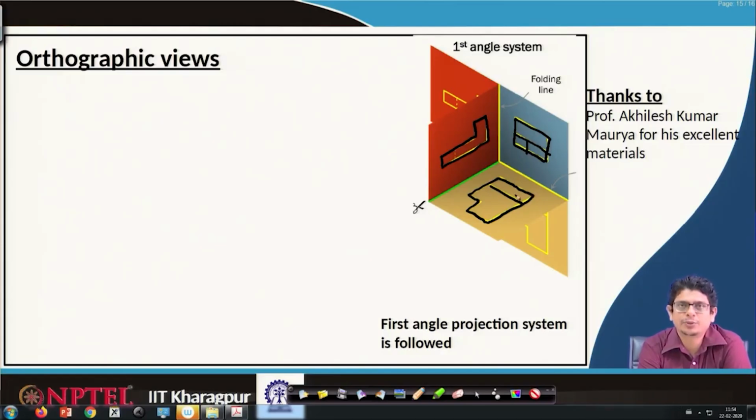The standard procedure is to first decide the vertical plane front view, after that go with the top view on the horizontal plane, and after that construct the side view, the profile plane view. So, here we construct the left side view and represent that. This is the way we go ahead.